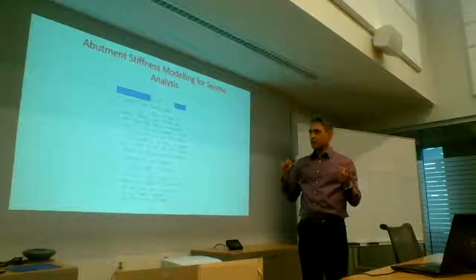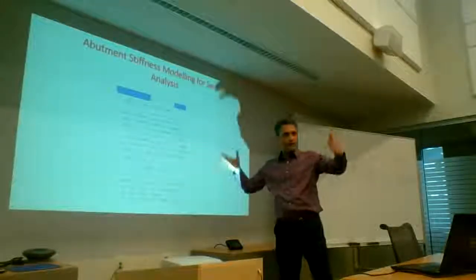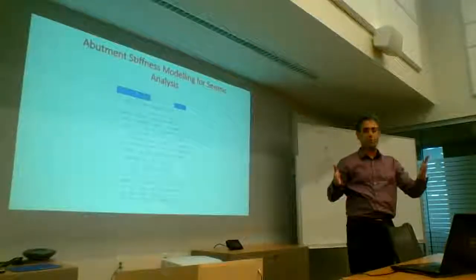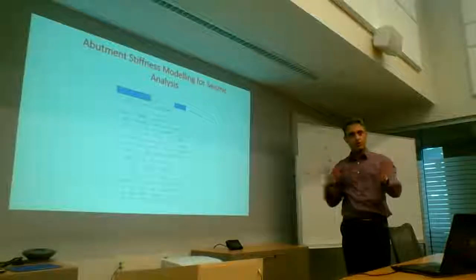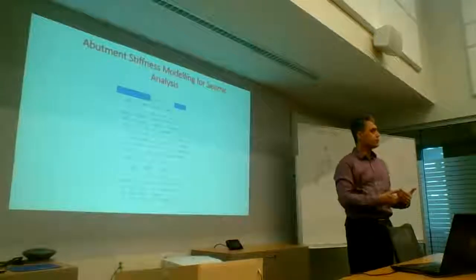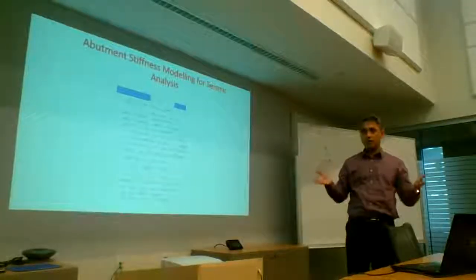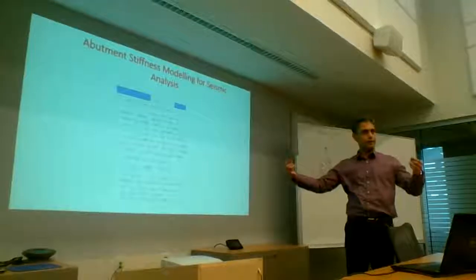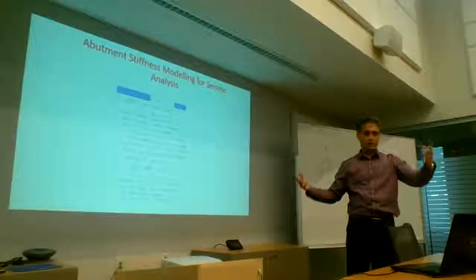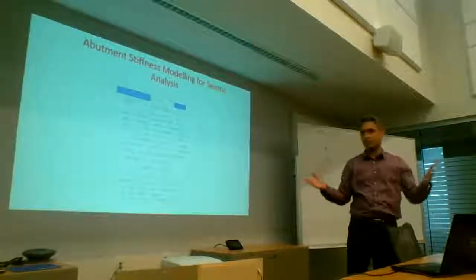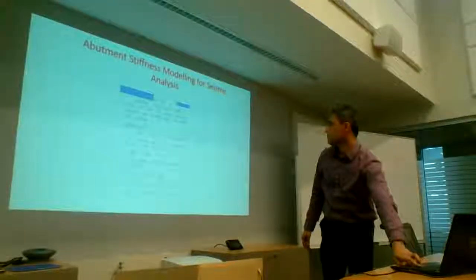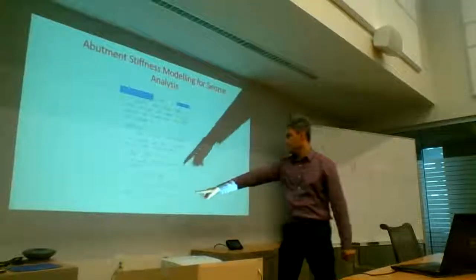Okay, so in a response spectrum, one trick you can do is to go with half and half the stiffness on either side, so your total stiffness is the same. So in design office, we have to come up with these sort of rational shortcuts to make sure that we're not doing something that doesn't make physical sense, yet be able to use the tool. Because this is not a tool where I can use a compression-only element, i.e. on this side as it moves, it's just doing nothing, because once you have a thing, it's active in both tension and compression. So we go half and half, and we come up with the force.